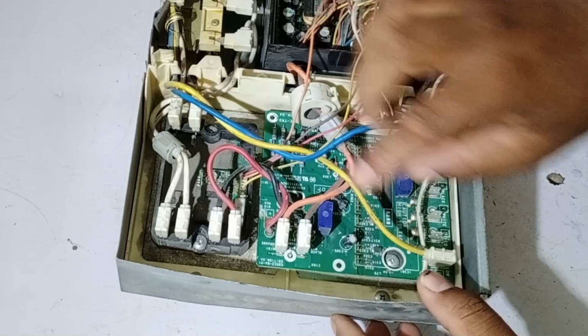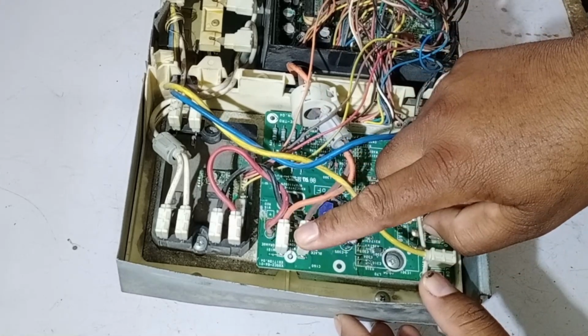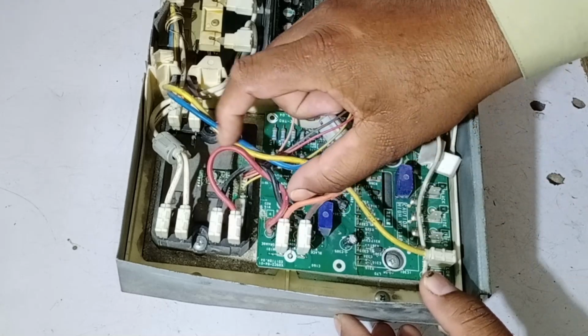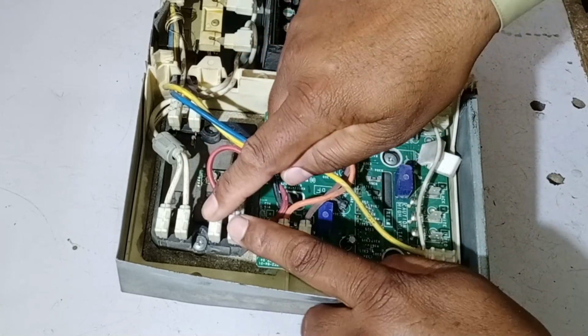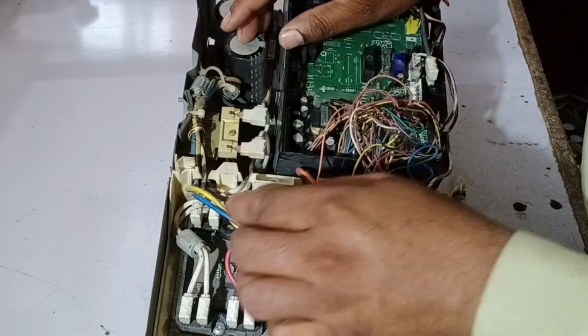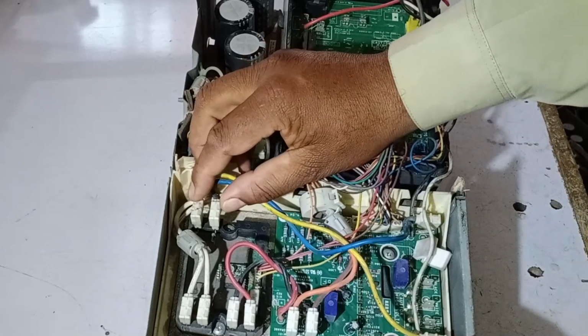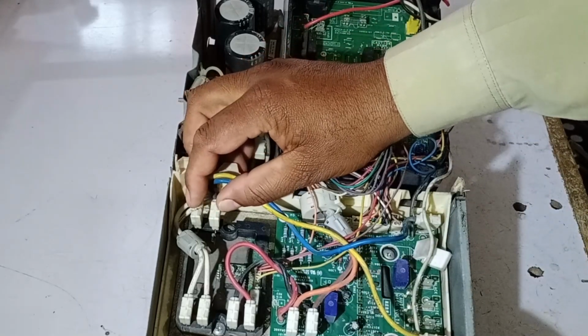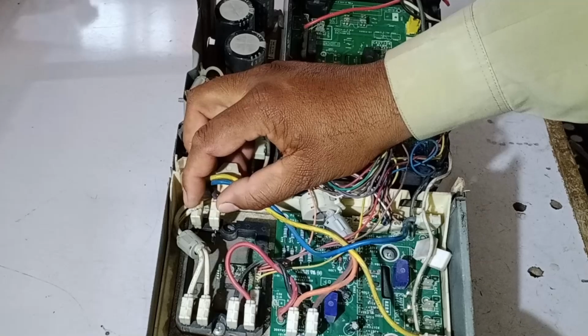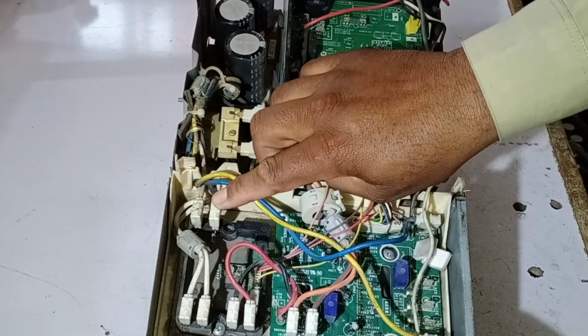Step 2. Checking voltages in the power circuit. First, check this point. It should have 220 volts AC. Once the power flows through, it should be rectified to 220 volts DC. As the current returns from the reactor, it should measure 320 volts DC in standby mode. When the unit is running, this voltage should increase up to 380 volts DC. If the voltage is higher than 380 volts, then the filters or capacitors are faulty and need replacement.